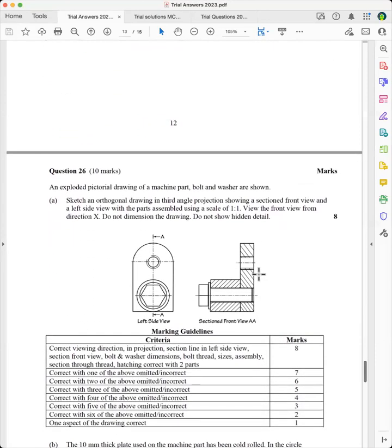And make sure that you know how to do a section drawing. Make sure that the section lines actually go through the thread if there's no bolt in the structure. But look down here, these section lines don't go through this bolt here, but they go through the thread there because there's no bolt there. And you're allowed to show only two faces here because the other view shows that it's a hexagon. And this is how you do an external thread. This is how you show what part is removed.